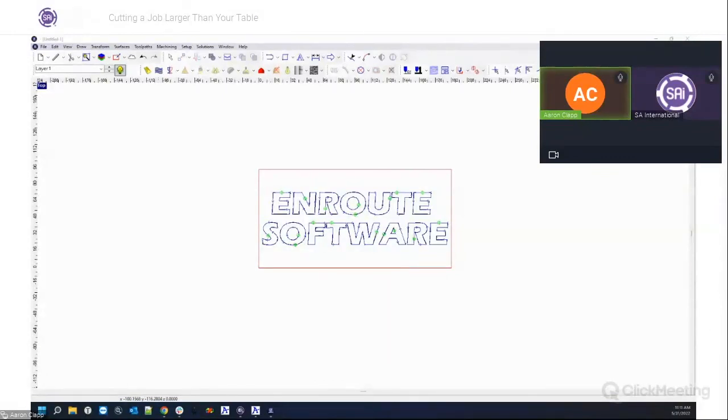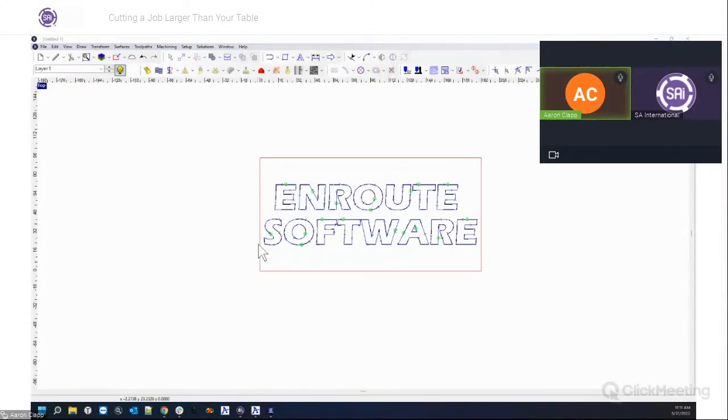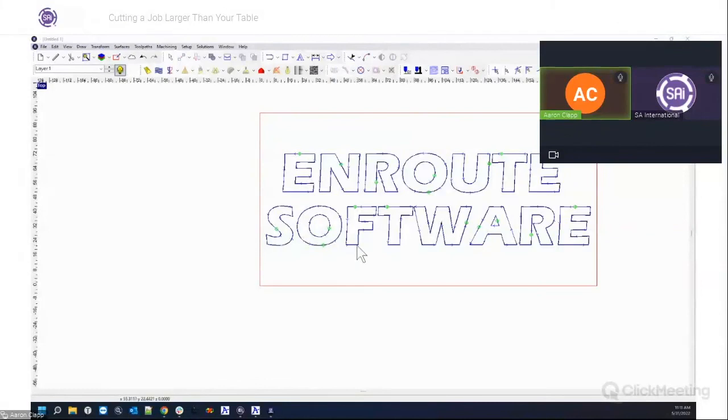It gives you a consistent place where you always know, okay, this is where it's always going to be, versus having to guess or assume, because there's no visual that tells me that's going to be my origin, like you have with the plate or with the user defined. With the user defined, it'll always be here. With the plate, it'll always be whichever plate you have selected. In this case, there's only one plate, so I have one. Whereas if I use this other tool, then I can choose which plate I want to have as my origin.